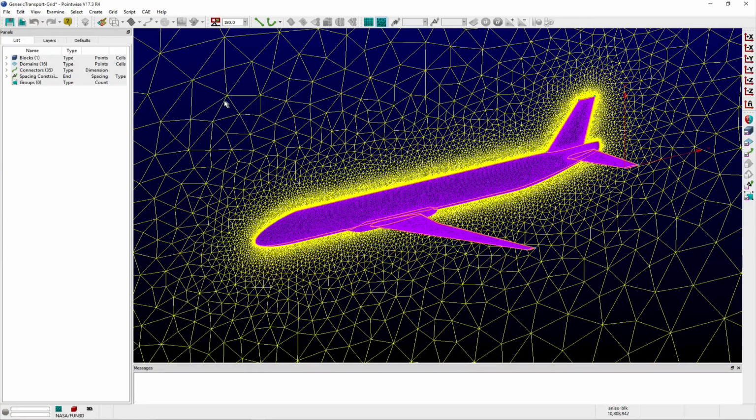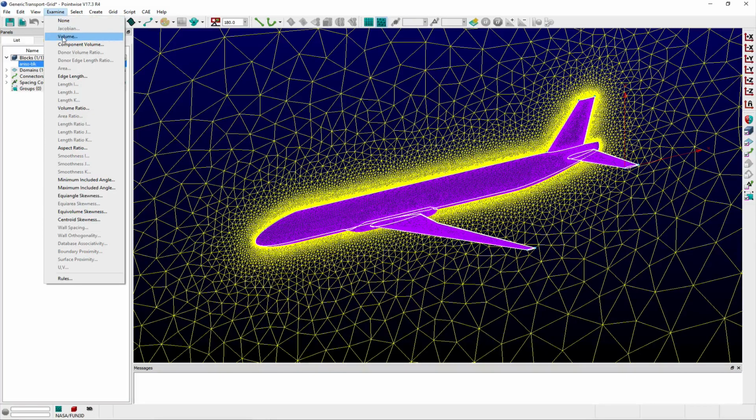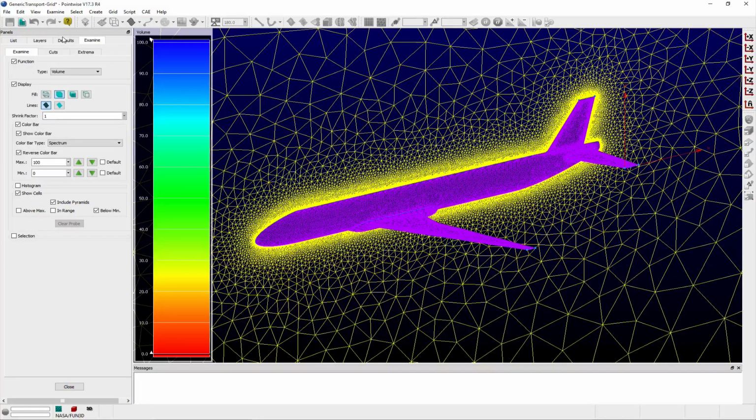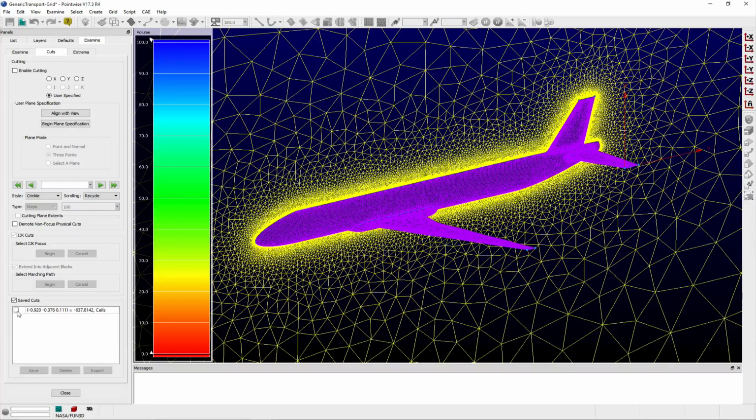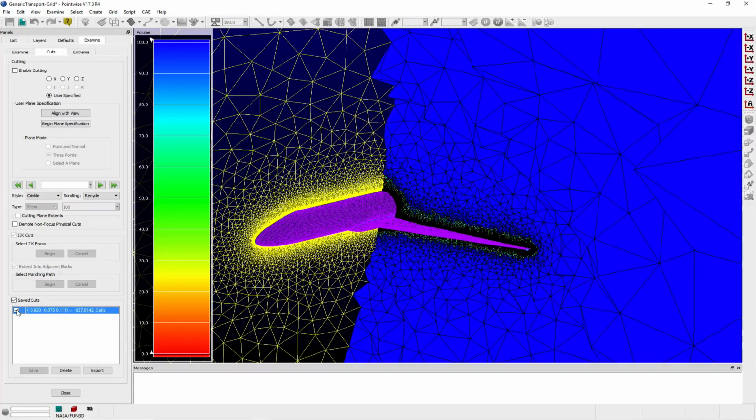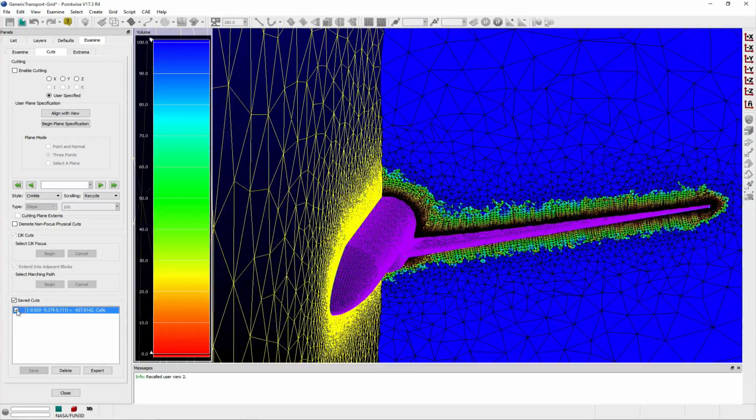Now, here's an important point about this process. If the underlying geometric definition were to change, but the assigned quilt names associated with that surface remain the same, then the script can be reused as written across any number of localized changes to the geometry. This means if I'm creating changes to the surfaces themselves, then I can reuse this script as is.